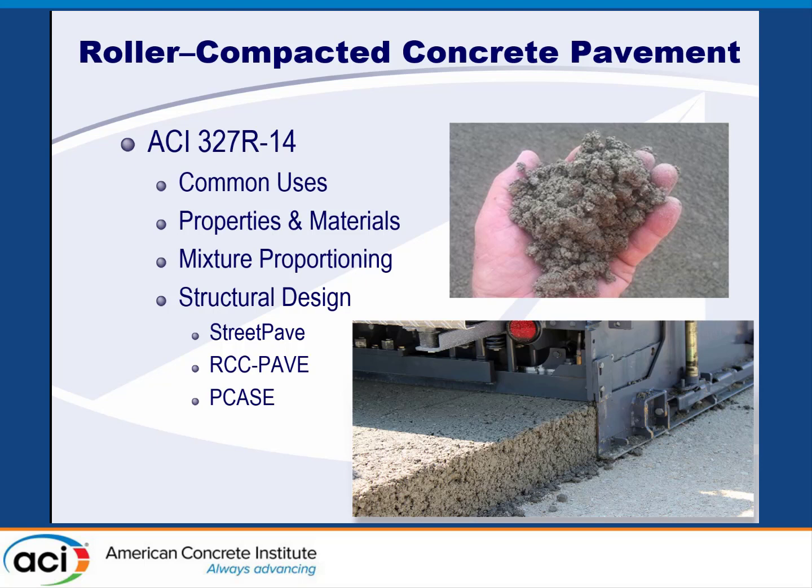And so it also goes through structural design, where it also uses a tool called the predecessor for Pavement Designer, which is StreetPave. So it's based on that same methodology that we'll talk about in a second with Pavement Designer. But it also talks about some other tools that are available for doing this type of work. It goes through RCC Pave, which is an older design methodology from the Portland Cement Association. I'm not sure that it's quite available anymore. It's really hard to find, but it can be used.